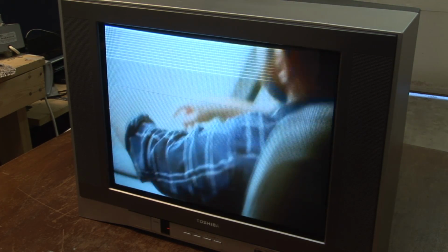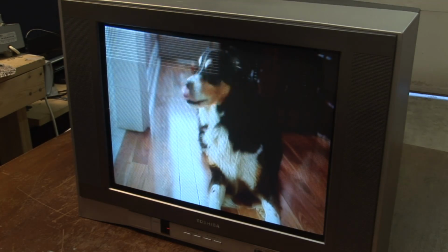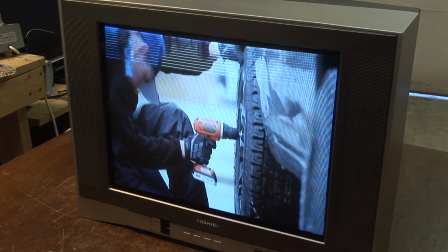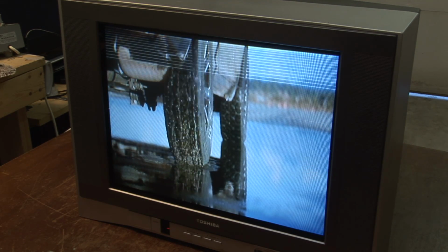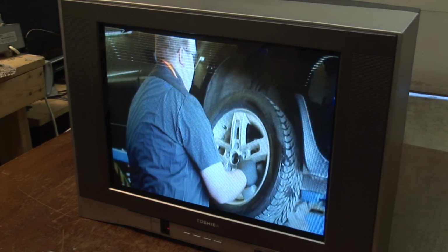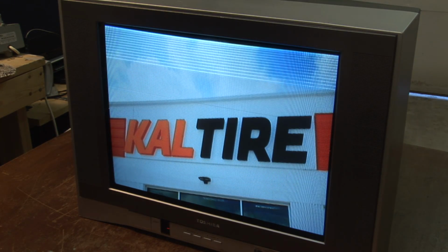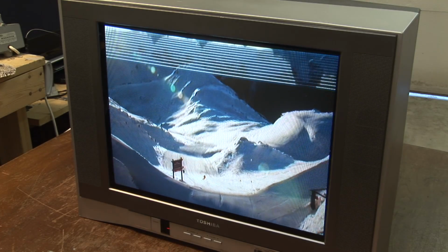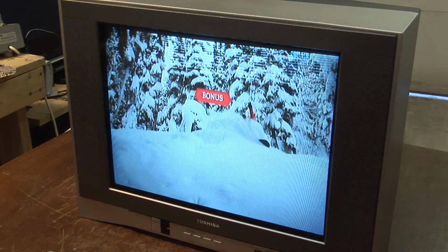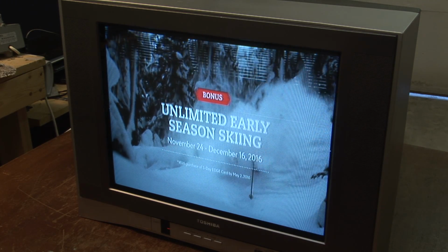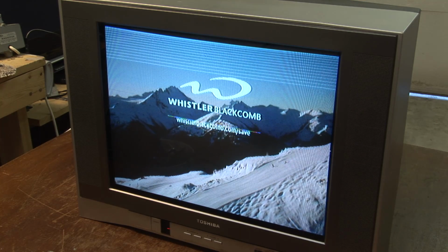that a CCD takes the entire image at once. It snaps an entire picture. All the lines are stored at the same instant in time, and then they are read out line by line. And in the case of, this is actually a 1080i camera. And some people will argue that 1080i or 1080 interlaced was not as good as 1080p. But that's not actually the case, because the sensor takes the shot all in the same 1/60th of a second.